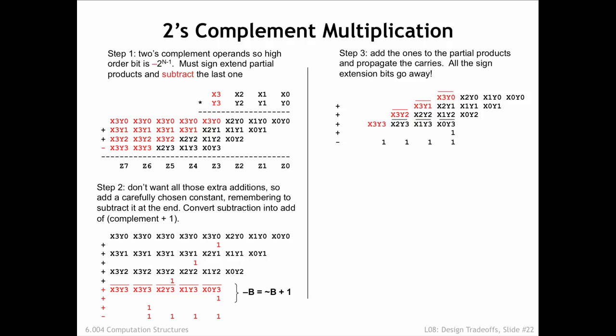On the other hand, if that partial product is negative, x3, y0 is 1, and all the sign extension bits are 1. Now when we add a 1 in that position, we complement the x3, y0 bit back to 0, but we also get a carry out. When that's added to the first sign extension bit, which is itself a 1, we get 0 with another carry out, and so on, with all the sign extension bits eventually getting flipped to 0 as the carry ripples to the end.